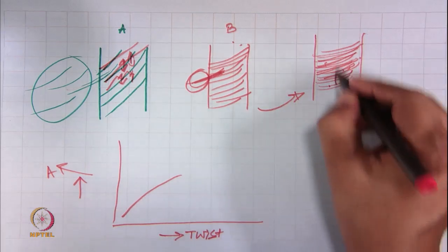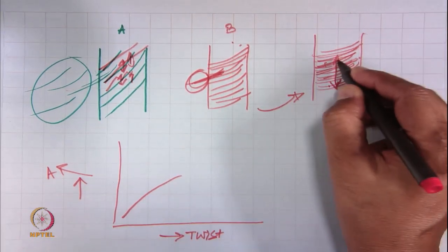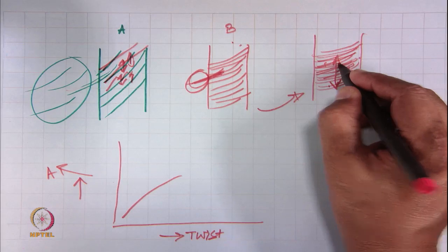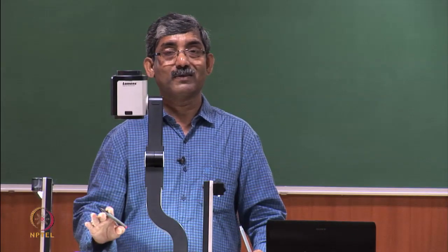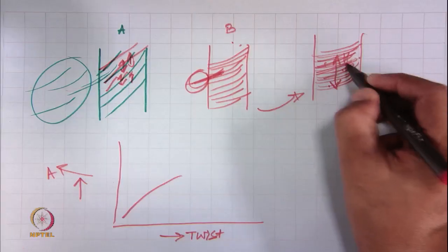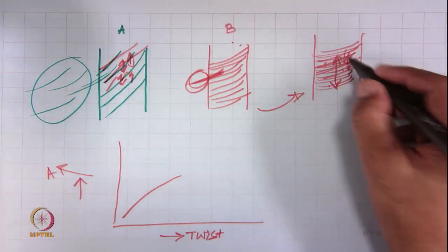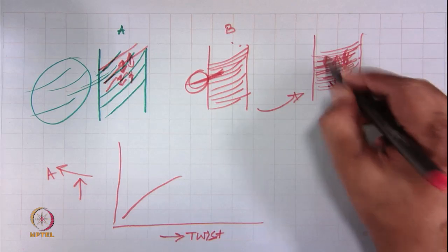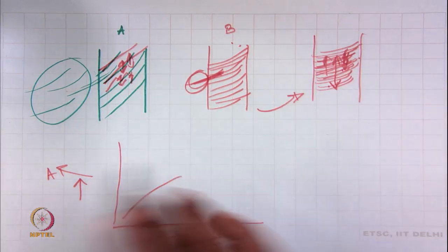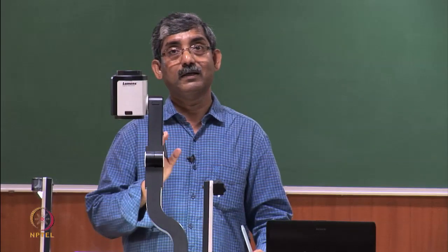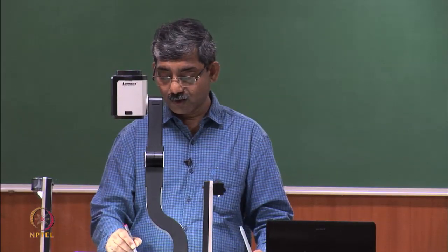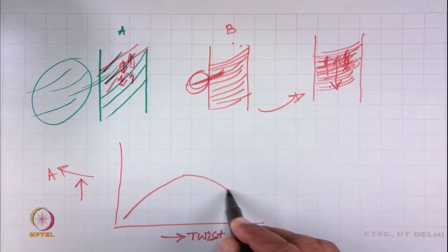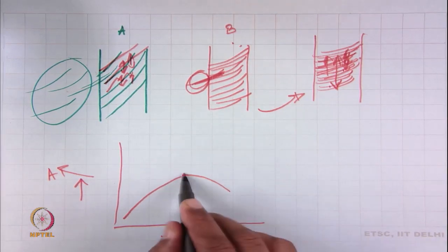So whatever abrasion is there will abrade the surface fiber too much, because there will not be any relative motion of the fibers. So, if the fabric is made of very high twisted yarn, then also you will see a drop in abrasion strength.